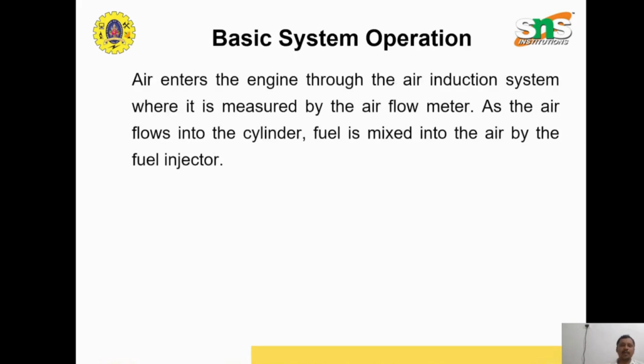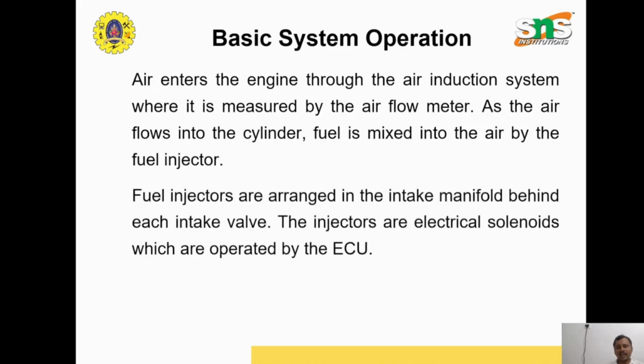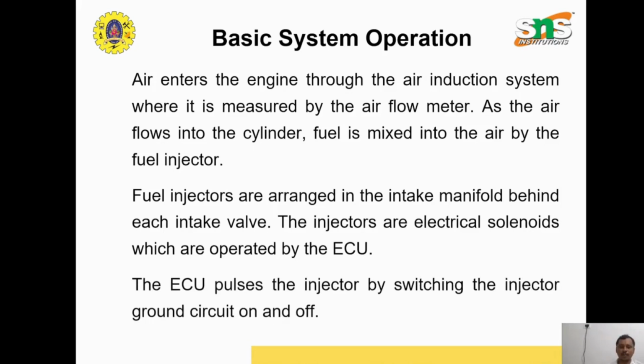Basically, the system operates as follows: air enters the engine through the air induction system, where it is measured by the airflow meter. As the air flows into the cylinder, fuel is mixed into the air by the fuel injector. Fuel injectors are arranged in the intake manifold behind each intake valve. The injectors are electrical solenoids which are operated by the ECU. The ECU pulses the injector by switching the injector ground circuit on and off.